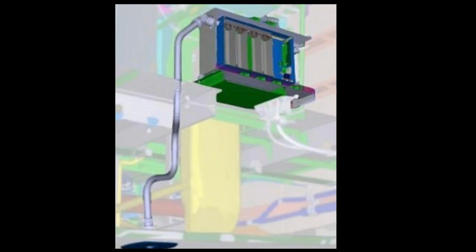Because this design fix wasn't just re-engineering that battery. In order to satisfy the authorities that that aircraft would be safe to fly if they did have another battery fire, they had to actually redesign the whole exhaust system. They had to encase the battery and create venting for it. So if the battery did catch on fire, they were able to contain the fire and exhaust all the poisonous gases out of the aircraft without hurting or killing people on the airplane or creating a major catastrophe of a plane crash.